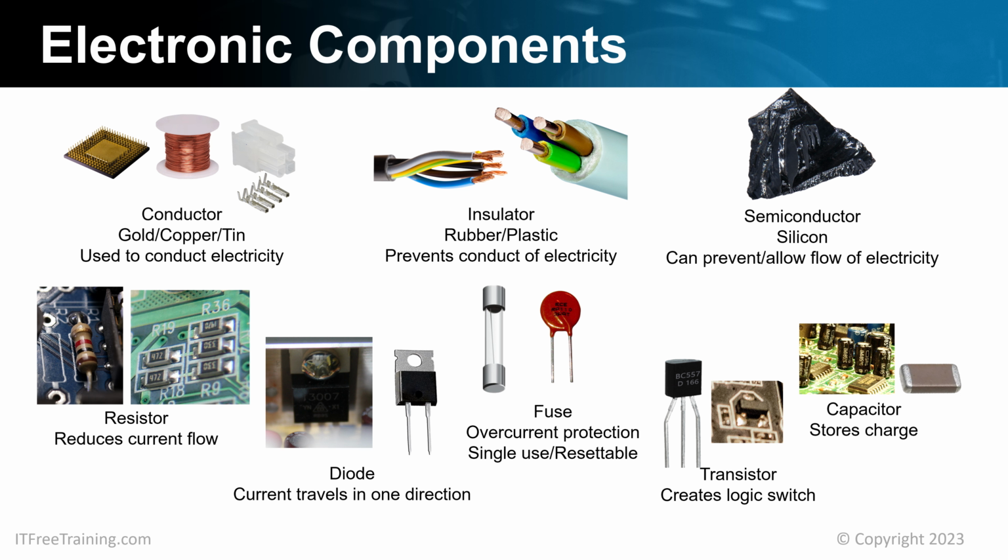You don't need to have a good understanding of electronic components. Just understand what to look for when something goes wrong. If your computer fails to start up, keeps restarting unexpectedly or shutting down, have a look at the motherboard and other components. A damaged capacitor will often have a buckled top and possibly the material inside may be leaking out. Other components may have burn marks around them indicating they are damaged. When you see this, it is time to replace the part.